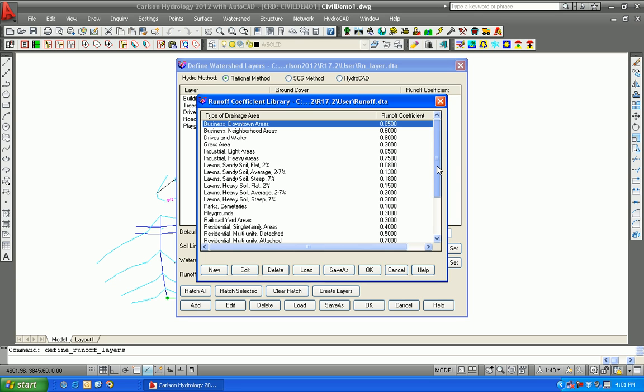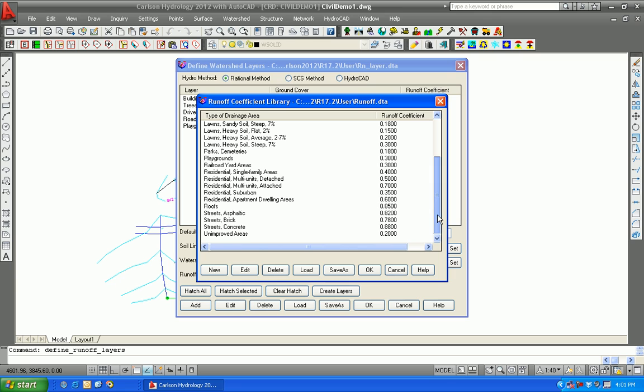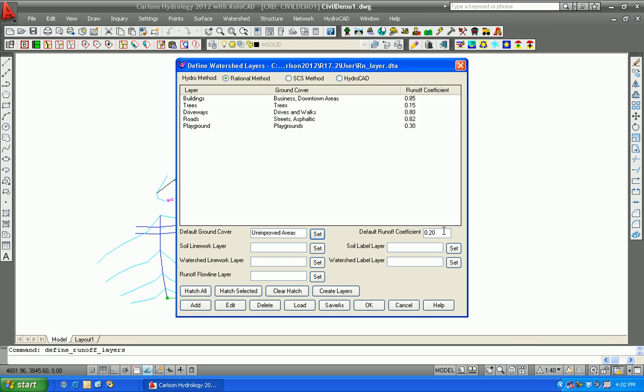But let's say this was a farm field with crops and perhaps, in fact, we can pick it from the default cover, and we can go and just say it was prior to the construction, it had an unimproved runoff coefficient of 0.2. All right, we'll just choose that. You can have a list that you yourself add to in terms of other zones. All right, unimproved, just part of a big farm, 0.2. And yet the 0.15 will still apply. We hit OK.